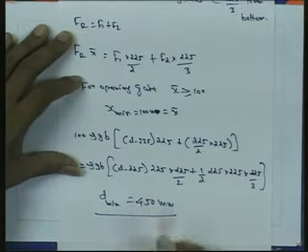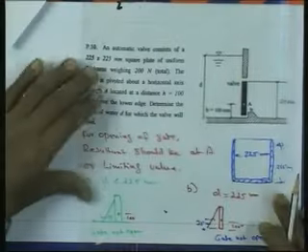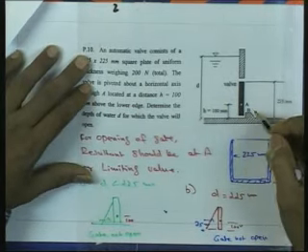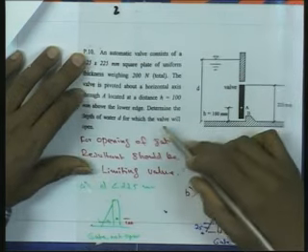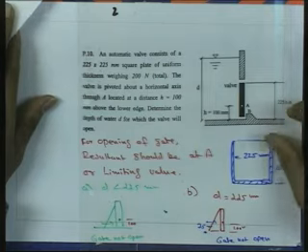Finally, we will see that the D minimum, that means the minimum depth of water to open this sluice gate, will be 450 millimeters. So, in that case the gate will be opening. So, finally, we can determine that the depth of water D for which the valve will open will be 450 millimeter.